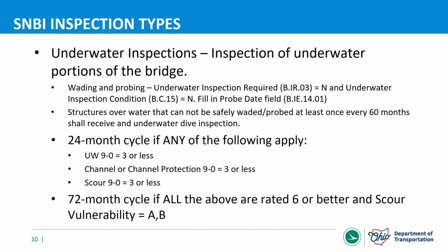If you are over a waterway, but you don't require underwater dive inspection, that is something we're tracking. If your bridge is over a waterway and it's marked as dive inspection no, then we will be checking to make sure the probe date field is filled out. That basically means you're telling me that you can inspect those substructure units in the water without an underwater dive. So we want to see that probe date field filled out.